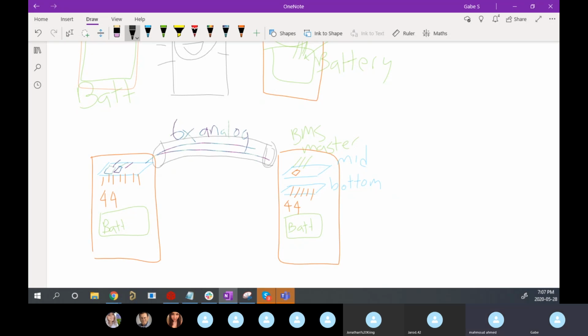Can I ask a question? Yeah. What about just having 2 thermistor expansion boards and just have the digital wires in between? Oh yeah, I was gonna ask as well. What's in the middle board? Because if it's just the ADC, you can just put a cheaper ADC on both of them, and just have 2 boards, one on one side, one on the other, and it'll be digital. Yeah, and then you can maybe do it with CAN or something, and it'll be more resilient to the noise going over the motor.